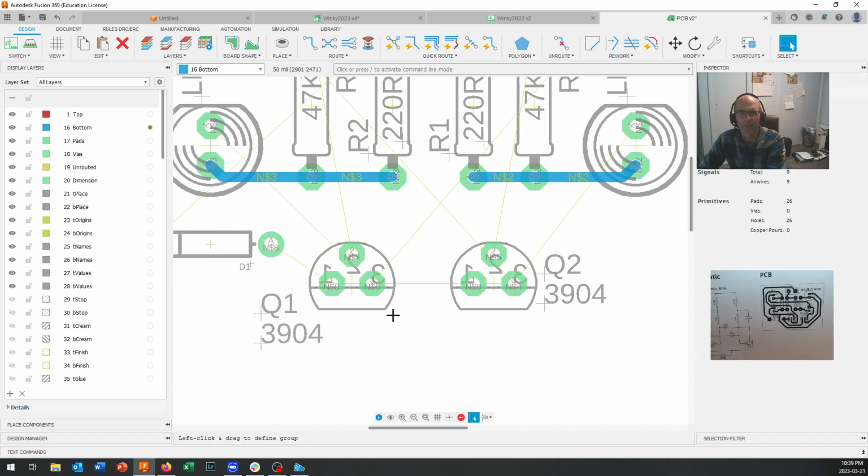And now when we look at this part from the top, we're looking down on top of our board from above. The traces that we're seeing are actually back behind the screen. Those are on the back of your screen. Those are underneath the entire circuit board. Those are on the bottom copper layer. Our components are on the top.